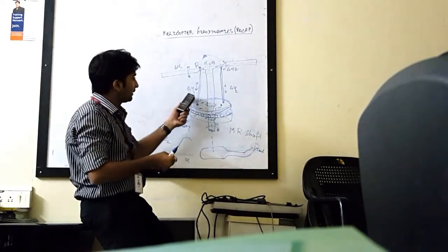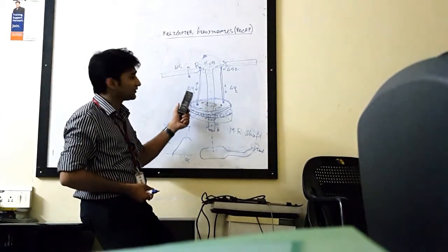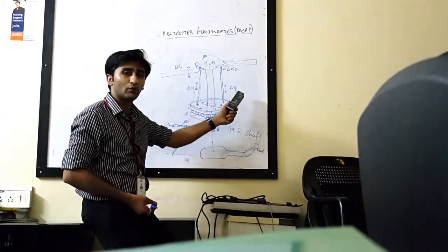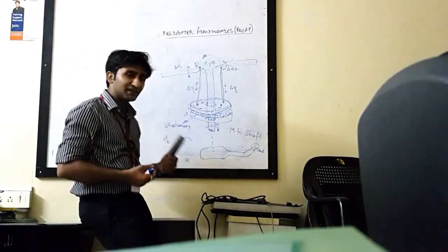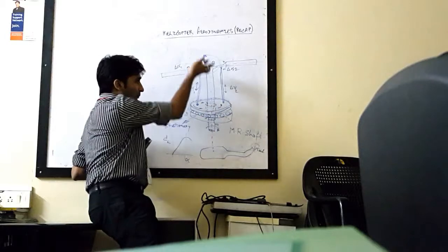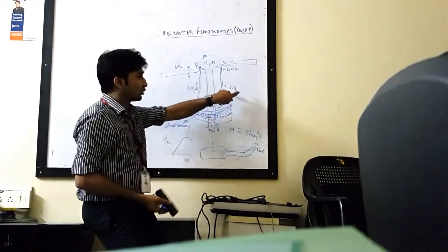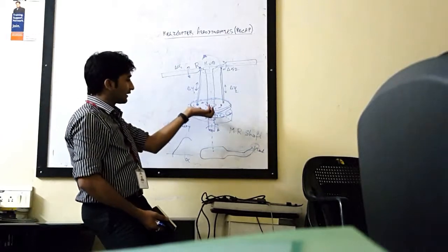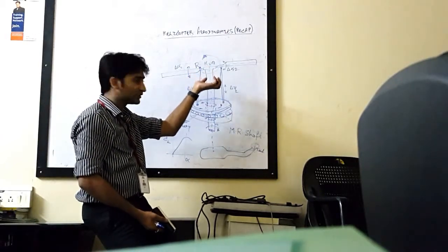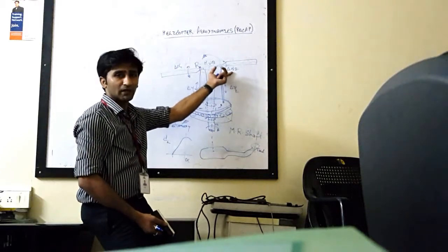So in vertical climb, delta y1 is equal to delta y2, and also in vertical descent you have delta y1 is equal to delta y2. Right? So how that is done is, this entire bottom plate is pushed up. When the entire bottom plate is pushed up, delta y1 should be equal to delta y2 because both are being pushed up simultaneously. So when delta y1 is equal to delta y2, delta alpha 1 will be equal to delta alpha 2.